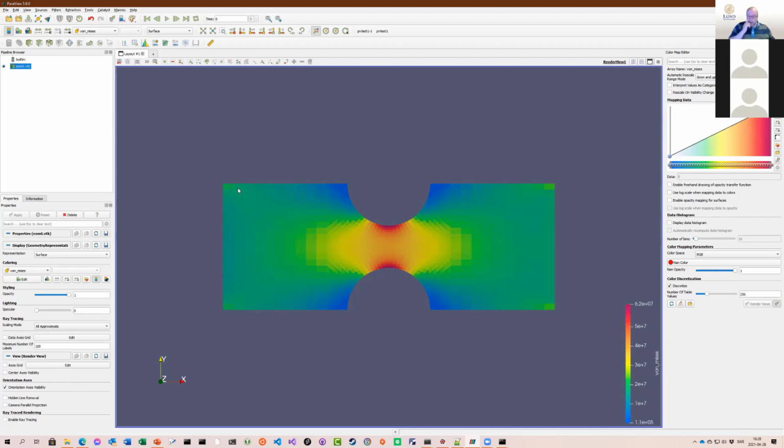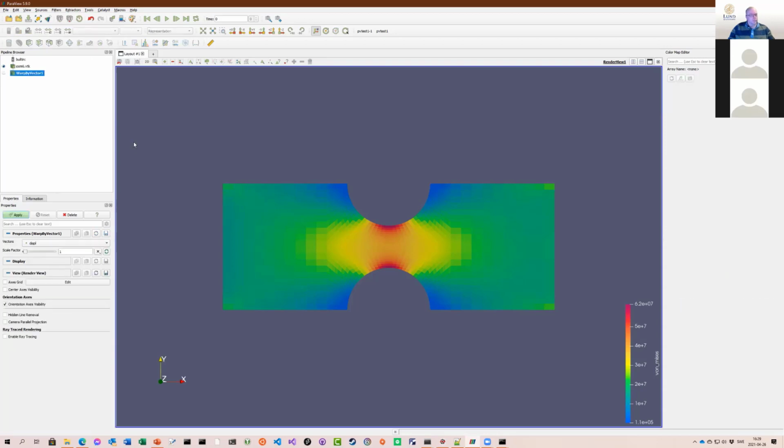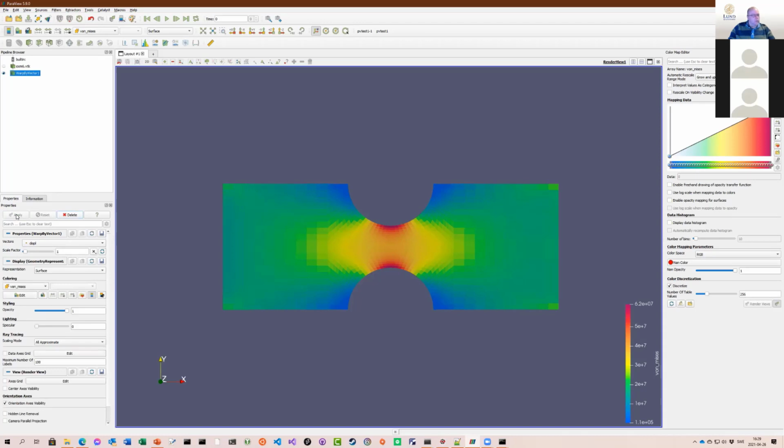Like that. So now we want to visualize the two more fields. We have a displacement field, and we can see here on the nodes we have displacement here as well. So let's see if we can add glyphs here. So that is a vector field, yes. So let's see if we can warp our structure. There is a special filter called warp by vector that you can use to apply a deformation on a structure based on a vector field. So let's do that, and you see it already pre-selected displacement here. So let's see what happens. You just apply here. Yeah, we couldn't see that properly.